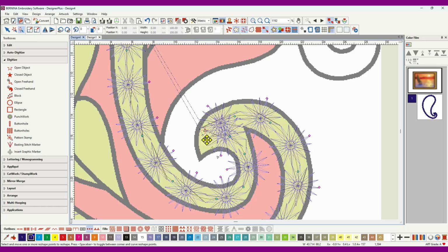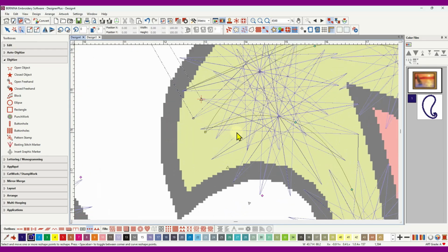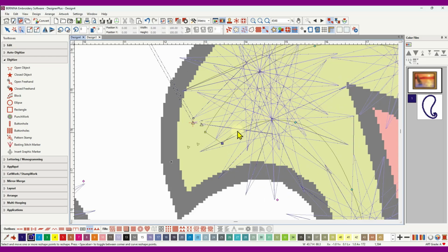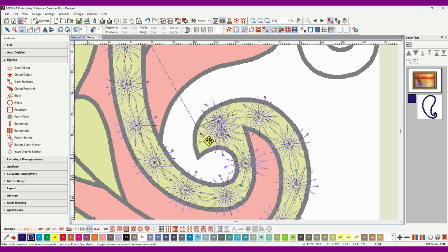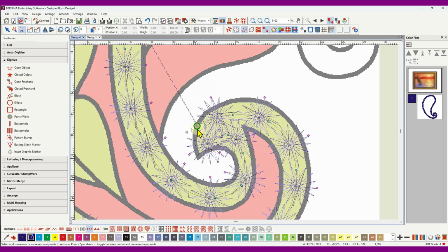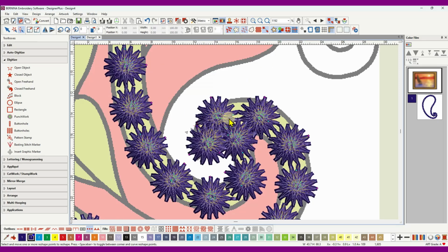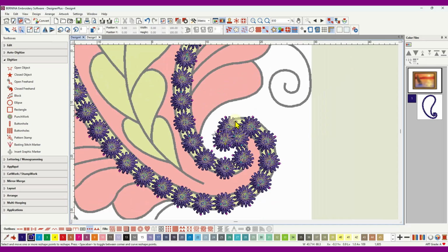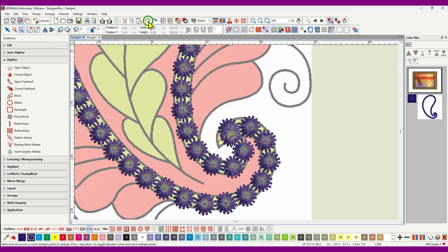Without dramatically changing the shape, you could try putting in another square node. Let me just get in here. Yes, there's the black line. So if I put another square node in there and bring it around like this, we still really haven't got enough room to spread these out. Oh, we're getting pretty close there, so you could fiddle around, but now I've got 3 nodes all overlapping. If I go into true view, it's better, but it's still all bunched up there. It's better with the shape, and if I spread them any further, I'm going to start running into these ones down here. So I'm going to undo that and undo it again.